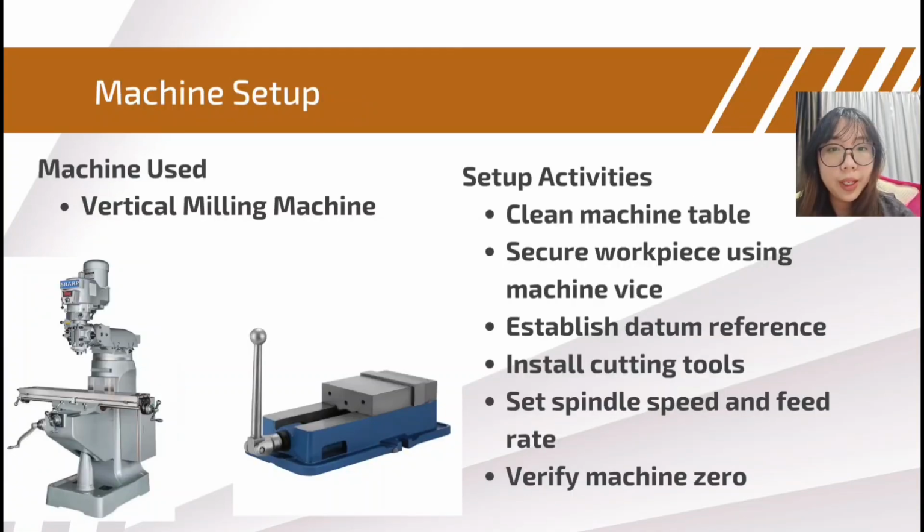Machine setup is a critical step because it directly affects machining quality. The workpiece was clamped securely using a machine vise. After establishing the datum reference, the cutting tools are installed and machining parameters are adjusted before starting the operation.